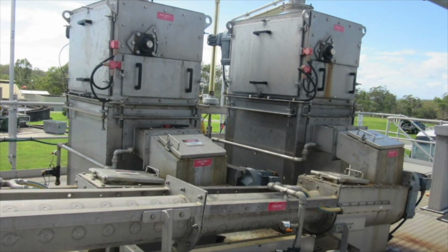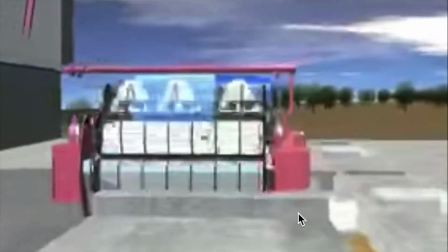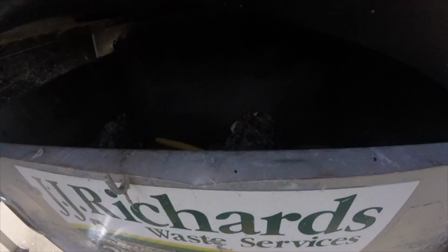Cleveland Treatment Plant uses an advanced twin-band screening system with 5 mm sieve openings to filter out larger solids from causing blockage or failures in the system. The band screens are mechanically cleaned by a rotating band which captures the chunkier rags upscreen and dumps them in the rag bin. The collected rag is later transferred to a designated burial landfill.